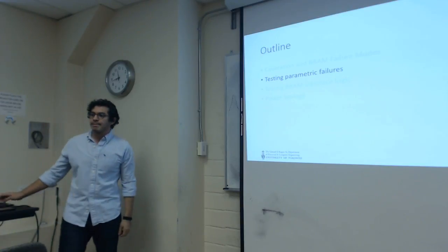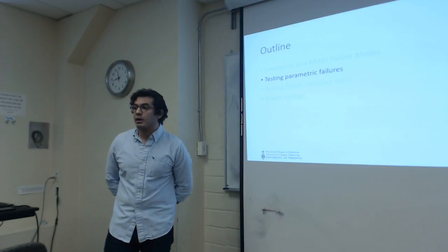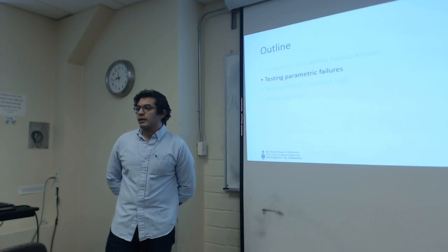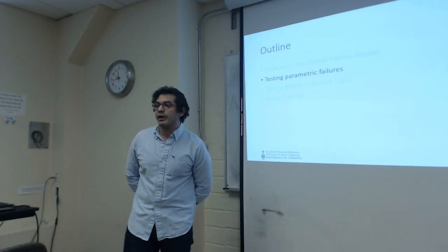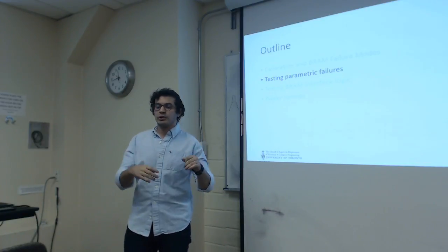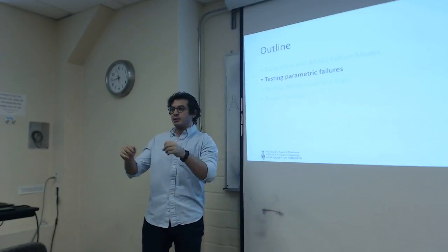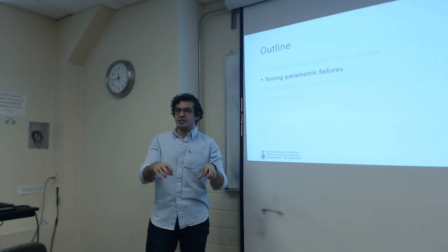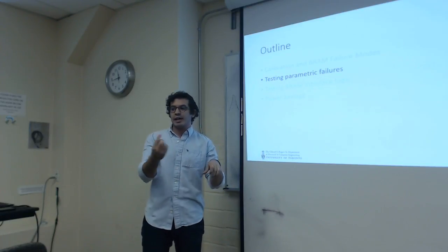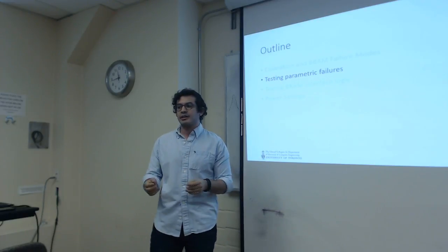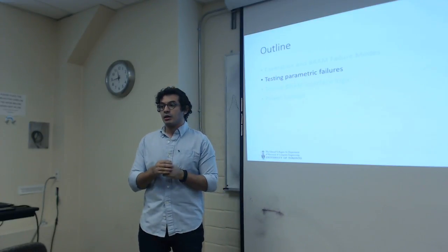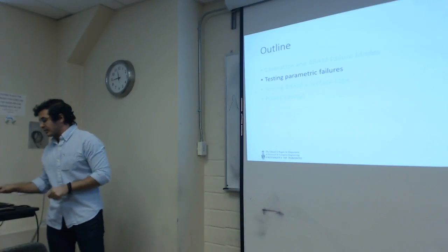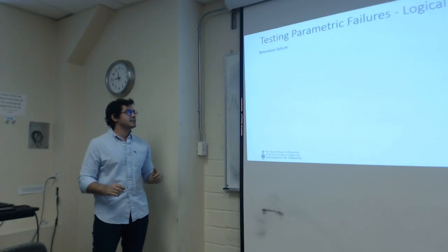Ibrahim, just to clarify, the calibration tables that you generate, that would be done right after manufacturing time, right? That would not be done by the user, is that correct? They would be done at the user side. So the user would give the application to the CAD system. The CAD system would generate the calibration bit stream, and using the calibration bit stream it is able to talk to a power supply that we have, and it will perform the whole calibration on the user side. And the calibration considers the design, so it's for that particular design. Exactly. So it's an application specific scheme.